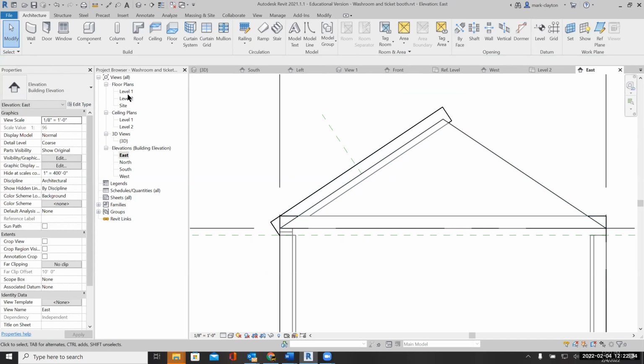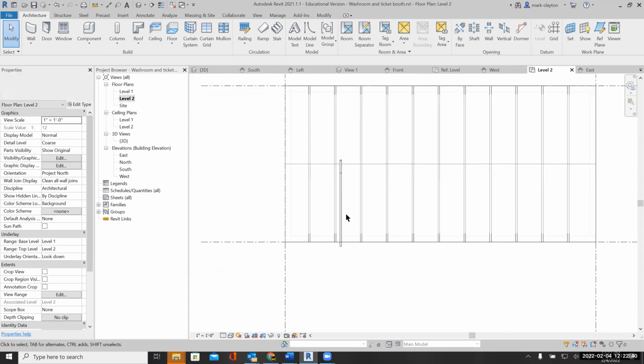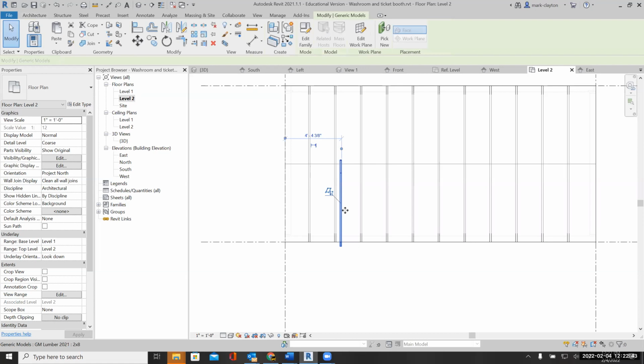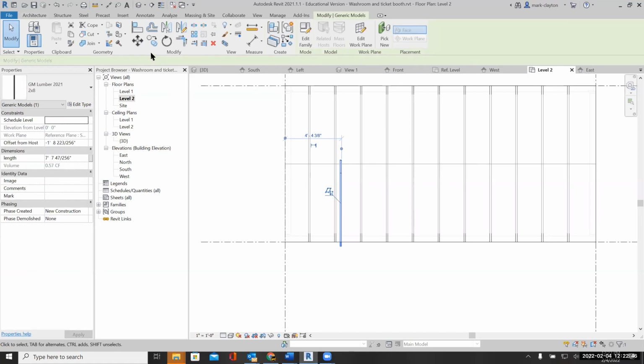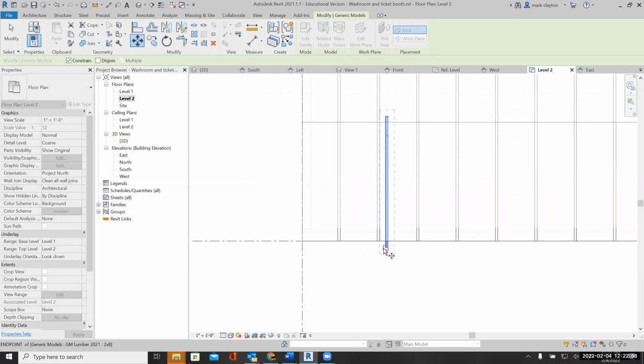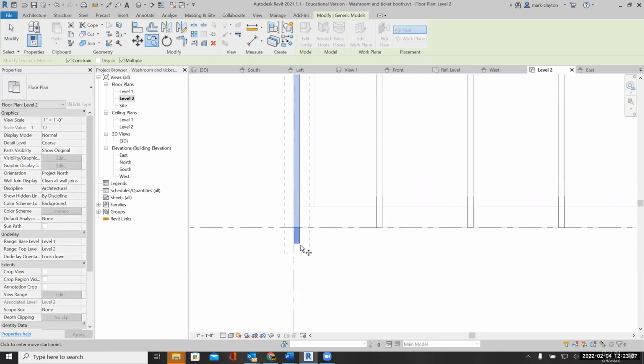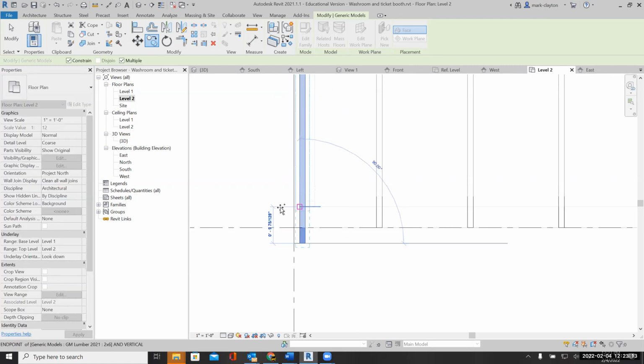And then I can look at it in my level 2 view, and I need to position it for this. And I'm going to position a rafter. I'm going to constrain it because I've got it about the right size, and a rafter here at the end. And I'm going to put a second rafter right next to it, so my end rafters are a little bit more developed than the normal rafter. They're doubled.